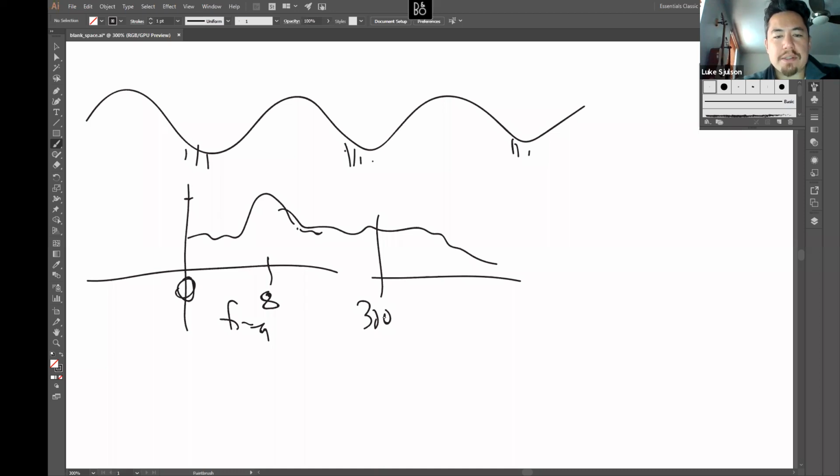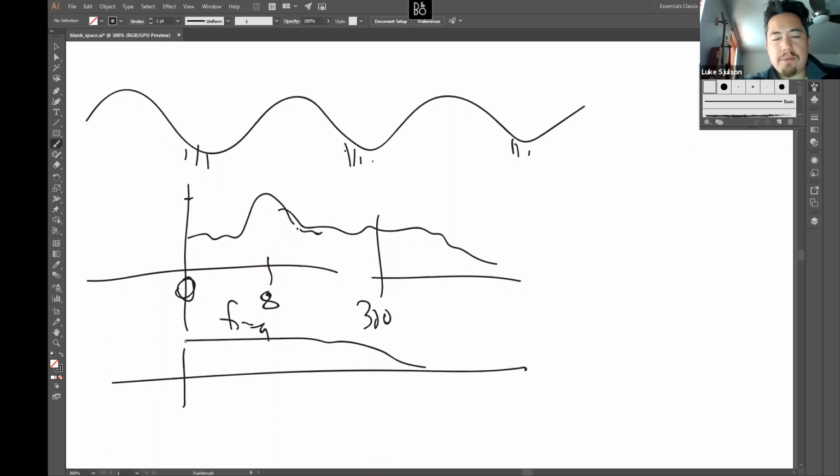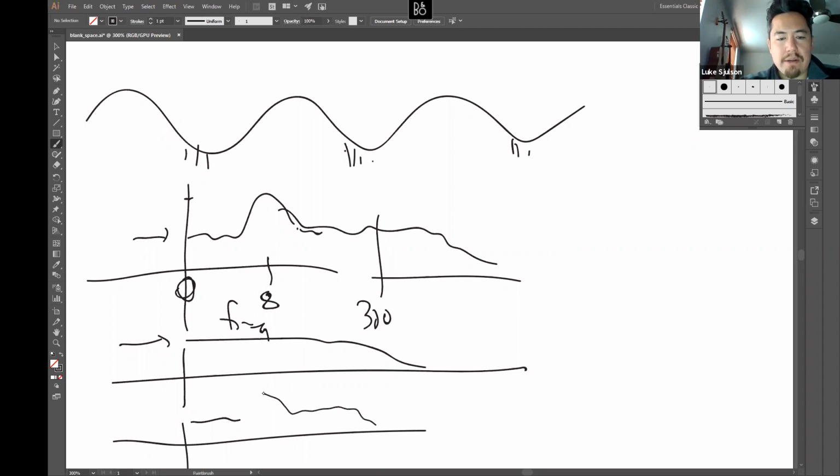A transfer function is something where, if you take that representation in the frequency domain, you can multiply it by, for example, a low pass filter. A low pass filter looks like that. That would be its transfer function, by which I mean that if you multiply this times that, what you'll get is something that looks like that, right? Out here are the spikes, and here is the theta and other LFP features. We'll talk a little bit later, when we actually talk about electrophysiology, about how they don't separate so nicely and cleanly, but for theta they do.